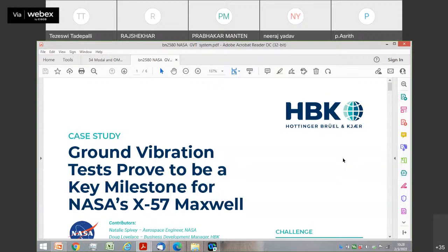But the thing at very high frequencies is, for those shock sensors, we have to do tapping and mount like that. On the barrel, we have to mount through the X60 bond. All the shock sensors, regrettably, come with permanent studs, because your mounting affects very much the response of the structure. If you mount with plastic or magnet at such high G levels, the sensor will just go off from the barrel. That would be the problem.